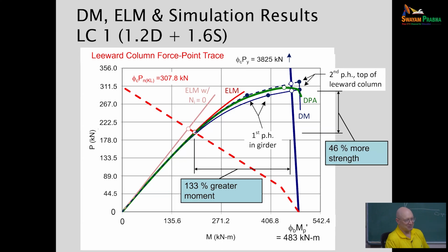Yeah, right. Pretty much a 0.9 phi factor on yield, a 0.9 factor on the elastic stiffnesses, and then as a judgment call, if you're running a plastic hinge-based solution, is that good enough to call it, oh, I'm capturing all the effects or not? The intent in Appendix 1 would be you'd use a 0.8 with the plastic hinge-based solution.